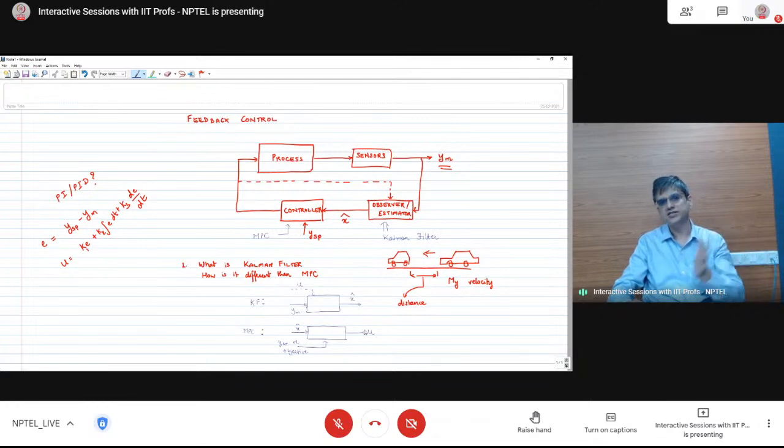It went from cloudy skies to really bright and sunny. So outside temperature increased from, let's say, 20 degrees Celsius to 25 degrees Celsius. In feedback control, you need to wait for the effect of that 25 degrees Celsius to be felt on the output measured variables before the input can make any corrective actions.